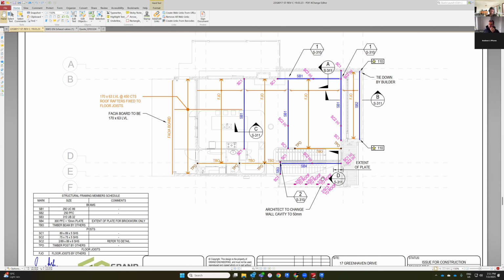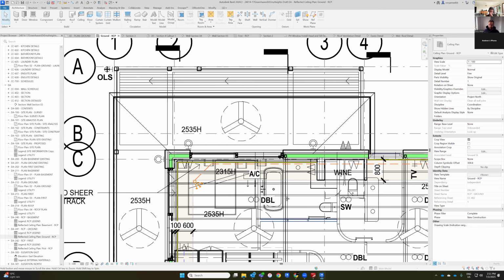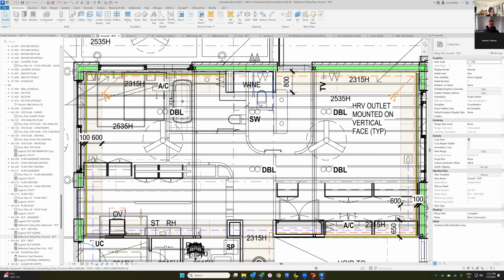And so I think that's why you wanted steel in there previously, to help brace, because we've got a big opening either end and it's all hollow. So that's a little bit why I've included these bracing walls at each side of the wine cabinet to help give some rigidity to it.